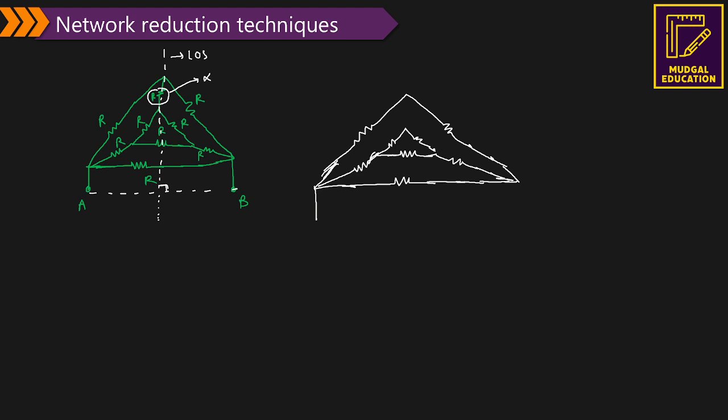Now the circuit becomes simple. You can solve it easily. Now how you can solve it? See very carefully. These two resistors become 2R. The bunch of these resistors is what? It is 2R parallel to R. So this becomes 2R by 3.